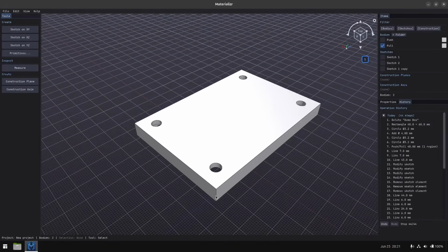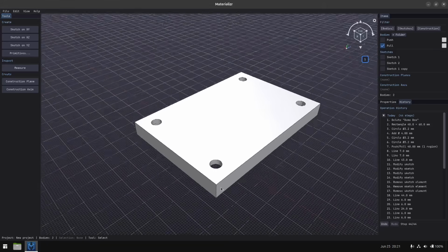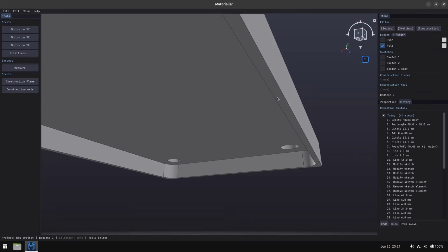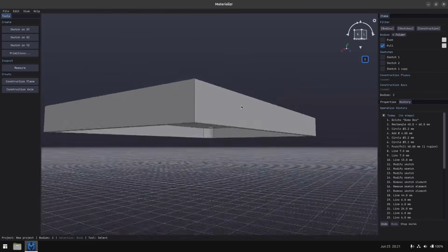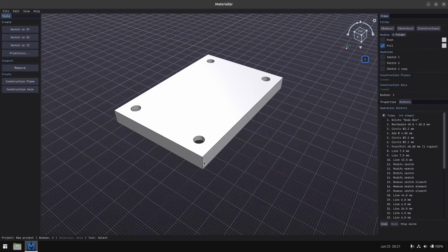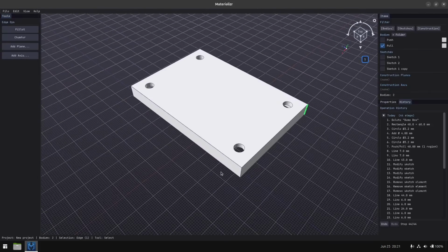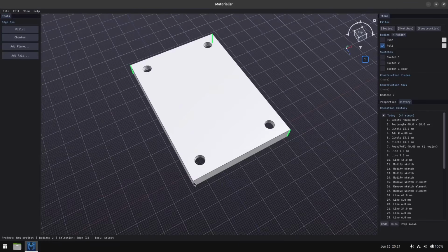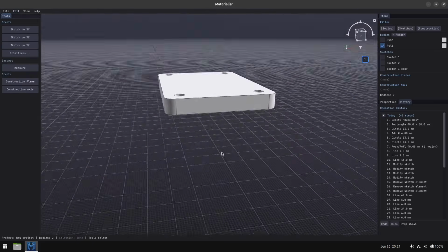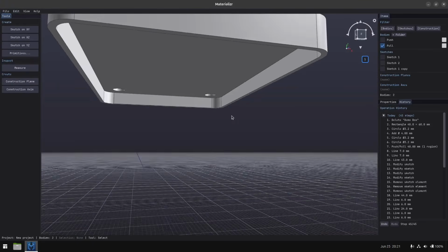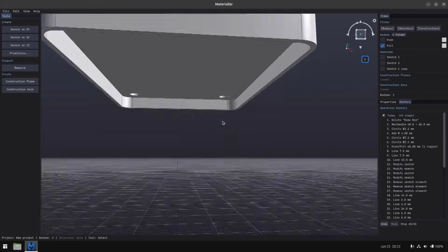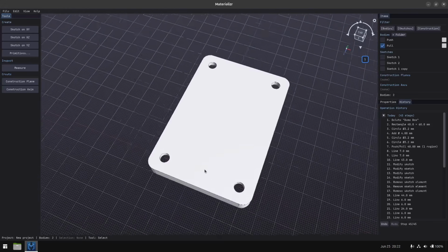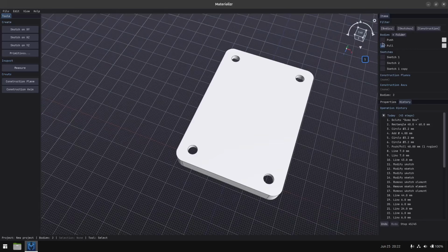And then, since this is a 1 millimeter thick wall that we've got here going all the way around, just to make it look neat, not really necessary or a hard rule to follow, I'm going to put all of these outside edges at a 4 millimeter fillet. And you'll see it here. It just looks nice. Alright, and that's a completed lid. Technically a completed box.